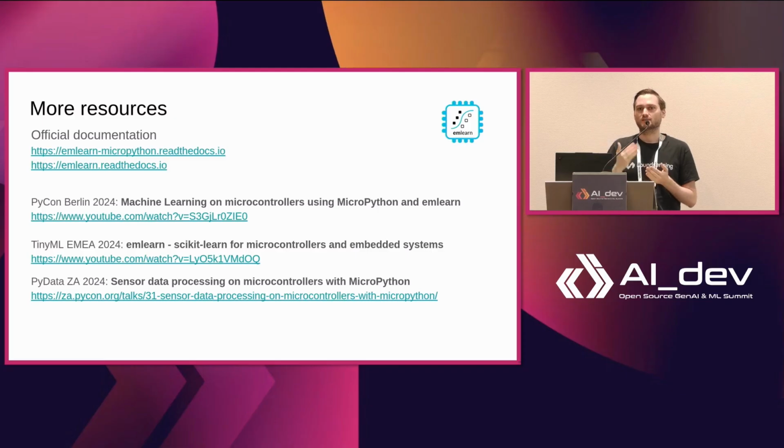But of course, if you don't have a good reason to go for a microcontroller, if you're in that area, it might be just easier to do it on a Raspberry Pi, a small embedded Linux type system. You can do it, but you should only do it if you need that power constraint, or you need the cost per device to be quite low. Otherwise, for image stuff, I would definitely consider going to an embedded Linux type device or phone if that can fit your use case.